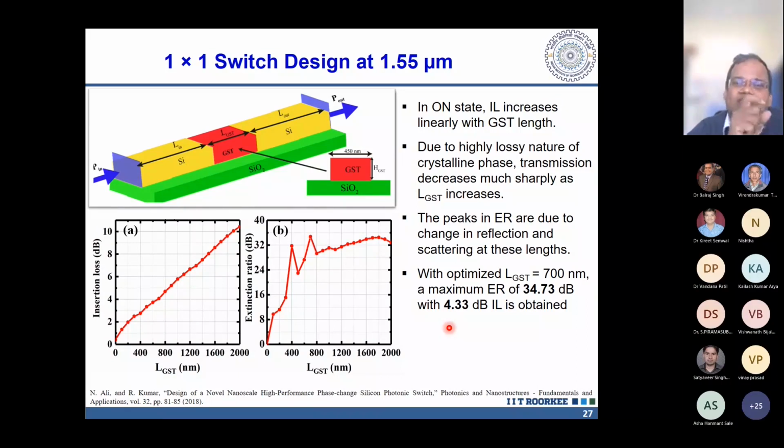The extinction ratio that you need for long haul communication should be a bare minimum of 10 dB. However, 30 dB or 45 dB, 50 dB is the preferred range nowadays. If you're talking of on-chip communication, for a short range, for a limited number of devices, you're fine with less than 10 dB. But if you set them lower, you pay the penalty in some other form. Bit error rate, etc. are basically linked to your initial extinction ratio.